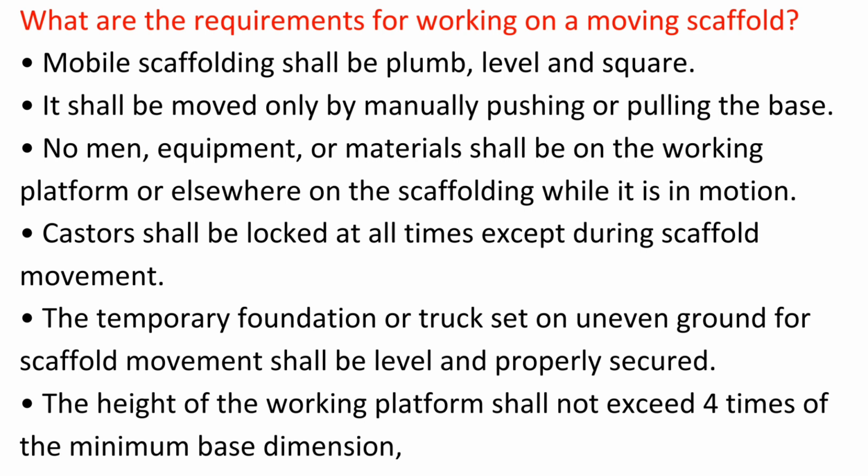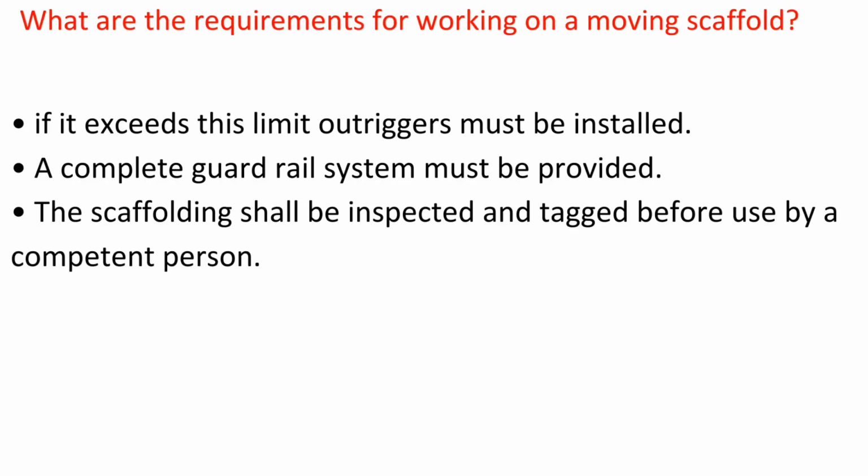The temporary foundation or track set on uneven ground for scaffold movement shall be level and properly secured. The height of the working platform shall not exceed 4 times the minimum base dimension. If it exceeds this limit, outriggers must be installed. A complete guardrail system must be provided.